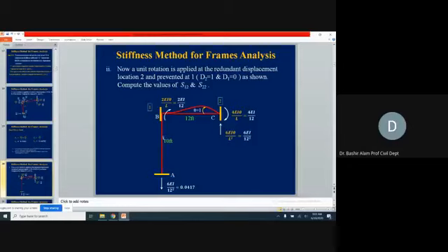Now you can see here, it is not going to allow this rotation to the BA member. In BA member, we don't have any kind of activities in terms of the displacement. So the corresponding moment is 0. And the shear forces are also 0. From where this 6EI over 12 square is coming, it is coming from this vertical reaction now.